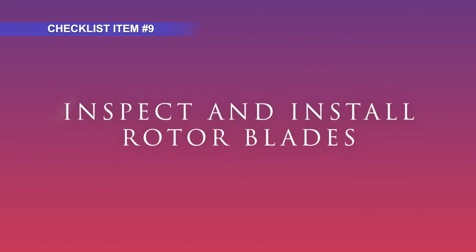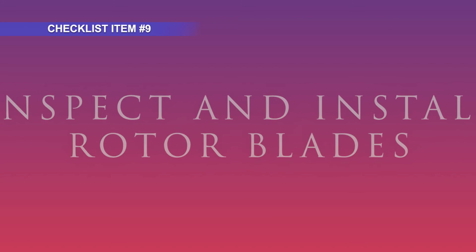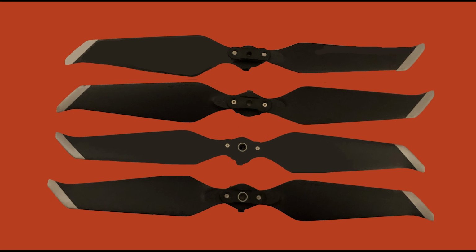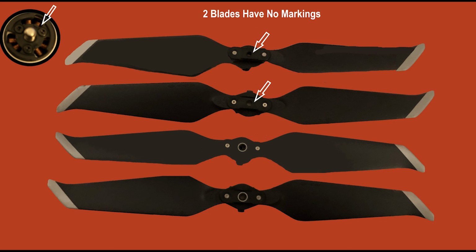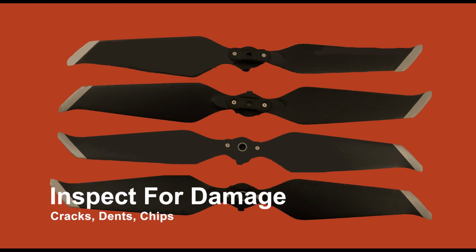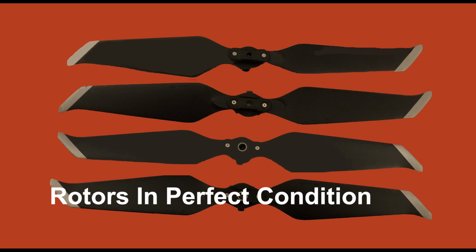Item 9 on the checklist is to inspect and install the rotor blades. A quadricopter has 4 individual blades that are divided into 2 pairs. Each rotor blade needs to be individually inspected for any type of cracks, dents, or damage, and your rotor blades need to be in near perfect condition.